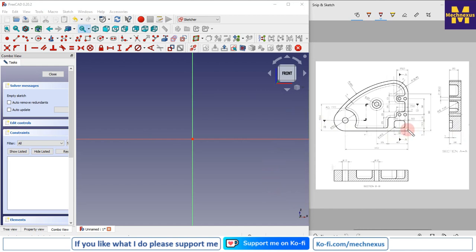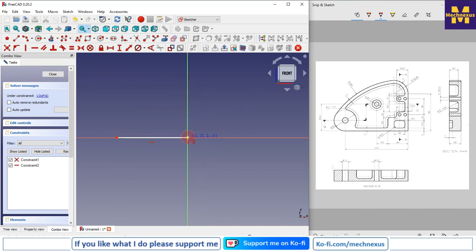So we will keep our origin here, select line, and I will draw one horizontal and one vertical line. And now I will give my dimension.